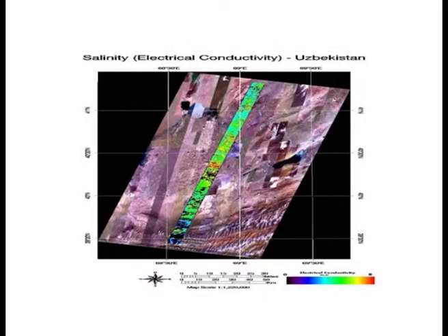These units or formations are generally described by their age, lithology, and thickness. Remote sensing can be used to describe lithology by the color, weathering and erosion characteristics, whether the rock is resistant or recessive, drainage patterns, and thickness of bedding.